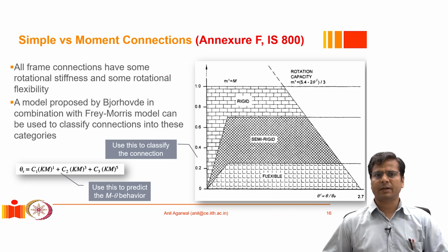Similarly, a connection that we might have designed as a rigid connection is made of some kind of an elastic material. All those materials can deform, and therefore any components that are used to make a rigid connection have some level of flexibility. Therefore, there is no true rigid connection, and as a result, we cannot classify connections as rigid or simple in a black and white fashion. We have to use a gray scale to basically quantify the level of rigidity. And there is a lot of research that has been done in this area, and it is a very established field already.